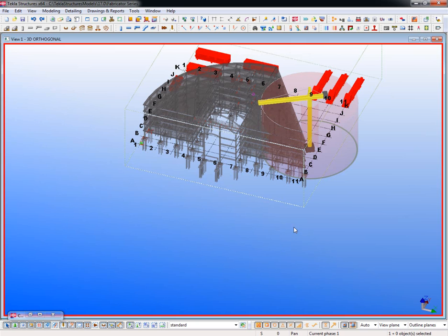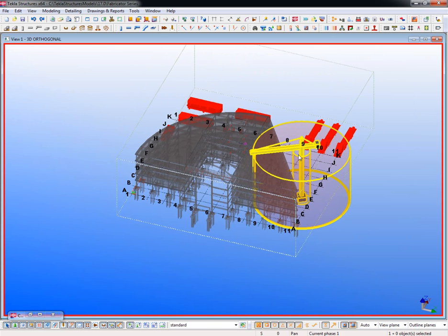Yeah, great point. But what you'll be able to do just by putting these in, you'll be able to generate the reach report, and then with a 3D model, you'll be able to also identify, like Ian was just talking about, any of these erectability issues. If you had a huge truss or a gravity column or something at the max radius of this, you'll be able to rethink that and reorganize that. But being able to visualize it in a model before a crane is ever out on site or something's in the air for you to find out that it's not going to work, obviously this will save you time and money to be able to automate that.